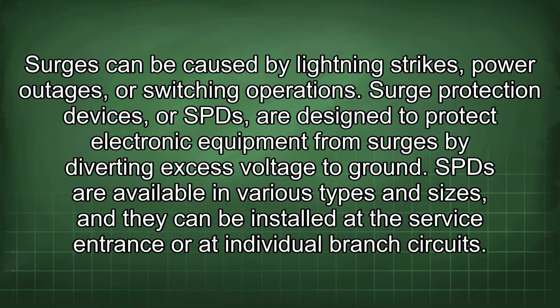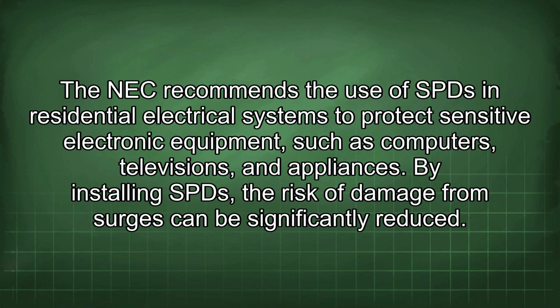SPDs are available in various types and sizes, and they can be installed at the service entrance or at individual branch circuits. The NEC recommends the use of SPDs in residential electrical systems to protect sensitive electronic equipment such as computers, televisions, and appliances. By installing SPDs, the risk of damage from surges can be significantly reduced.